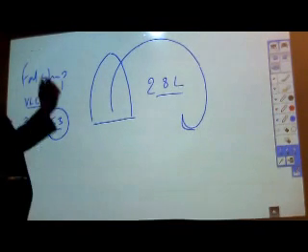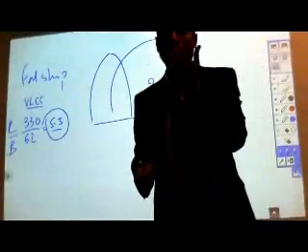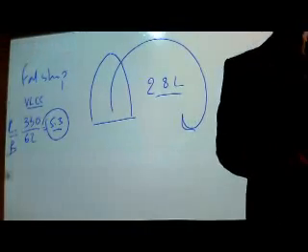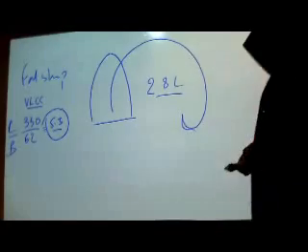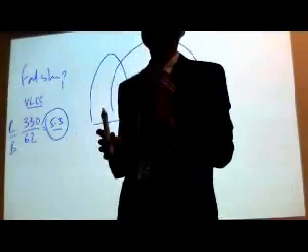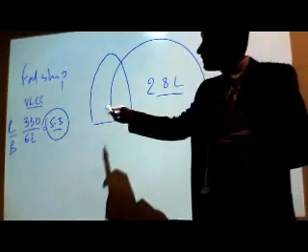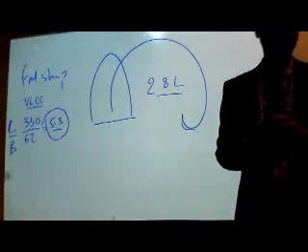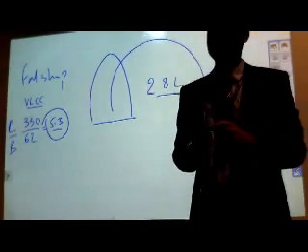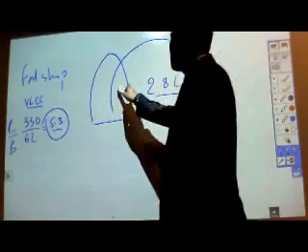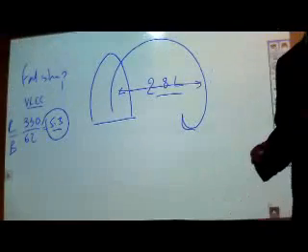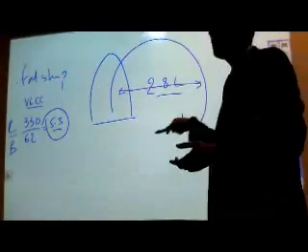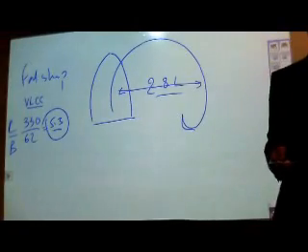It will not be directionally stable. It will need controllable factors: the steering will continuously need to be applied on this ship to keep it directionally stable, keep it going. But if you needed to turn it, well then it will turn quicker. Tighter turn. Quicker, of course it will be quicker because it is a shorter, tighter turn.